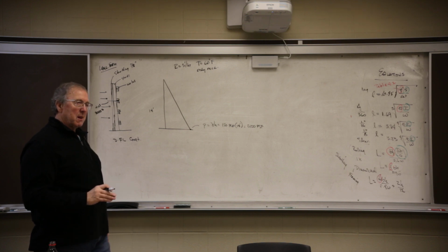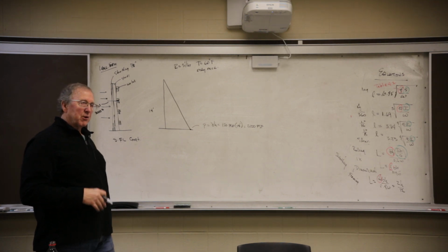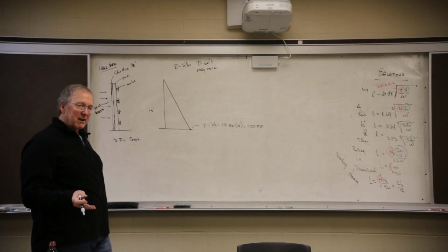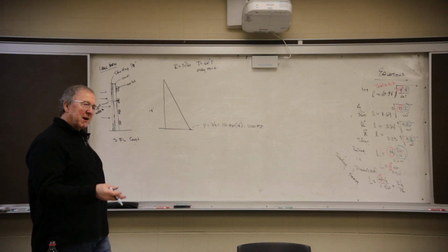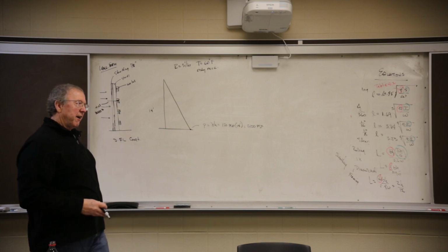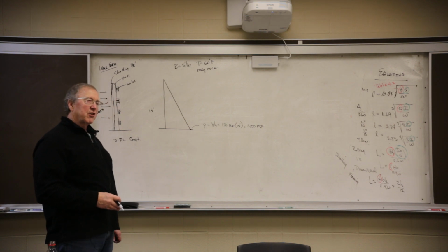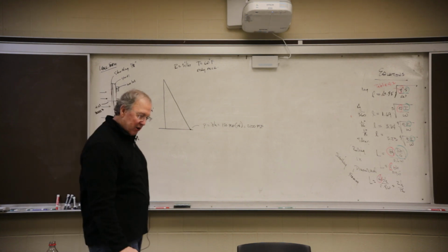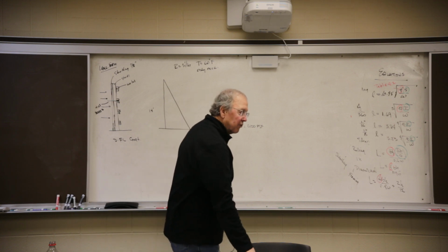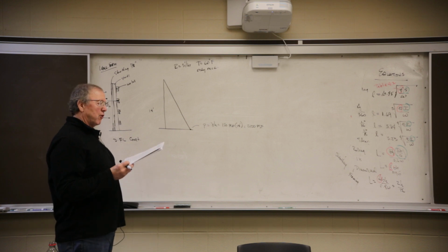So that would be what we would calculate if concrete was poured fast enough that it remained a liquid. Okay, the ACI code says that's not the case. When you pour it, it's going to start hydrating. When it hydrates, it's going to go from a liquid to a semi-solid to a solid. Therefore, as we pour, part of that liquid is going to turn into a semi-solid, decreasing the horizontal load. So the table on page 512 gives you the maximum force that can be exerted on the form sideways.